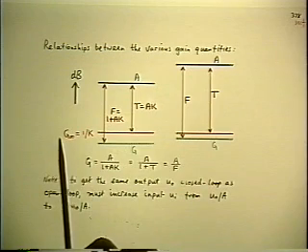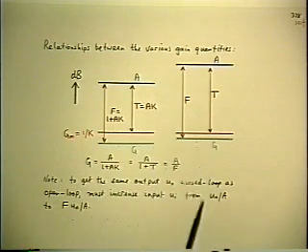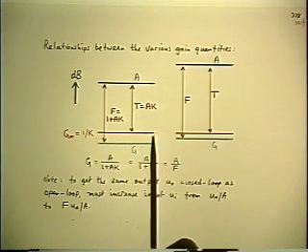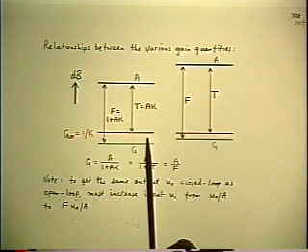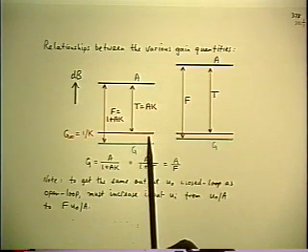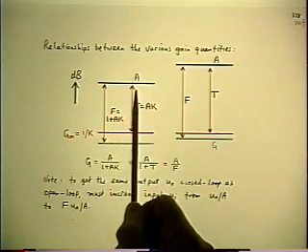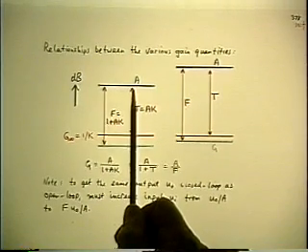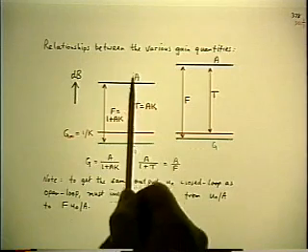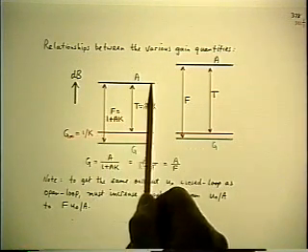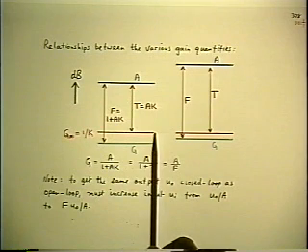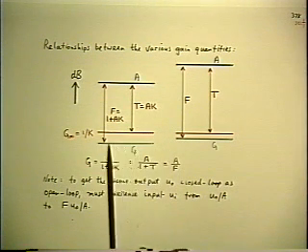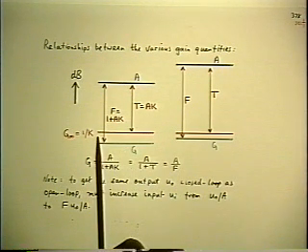Let's start with the specification, the G infinity. The vertical axis is various gains in dB as usual. So I've drawn G infinity, the specification, at some arbitrary level. If I'm going to build a feedback amplifier that's going to have a closed loop gain which is close to G infinity, then I better start with a forward amplifier that has a lot more gain than that, because I know feedback is going to lower it. So I better start out with some spare. So I'll start with an A which is bigger than the G infinity. And the result of that is I'm going to end up with an actual closed loop gain that's going to be a little bit less than the G infinity.